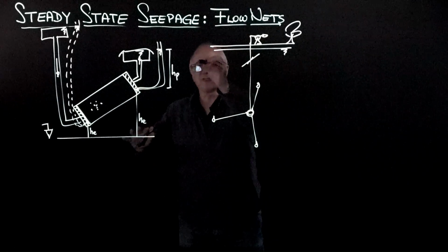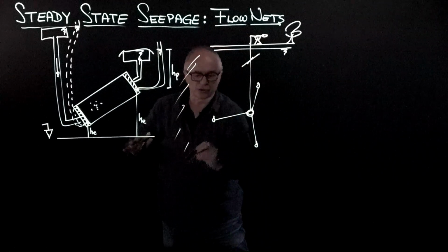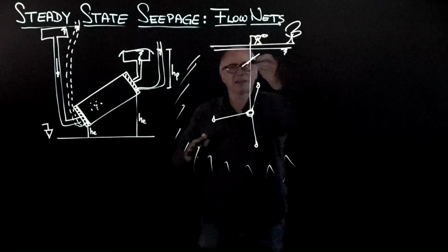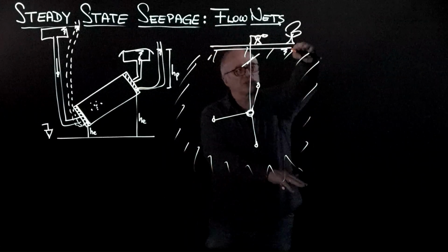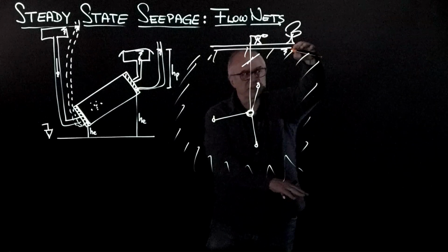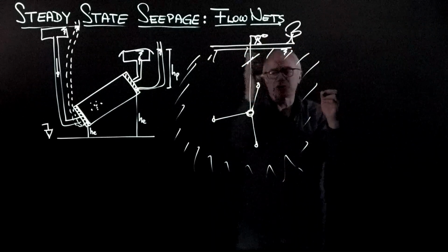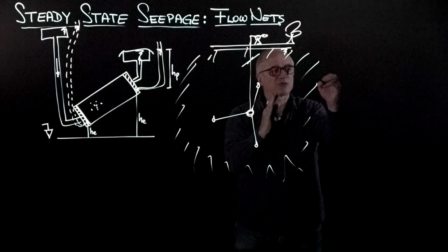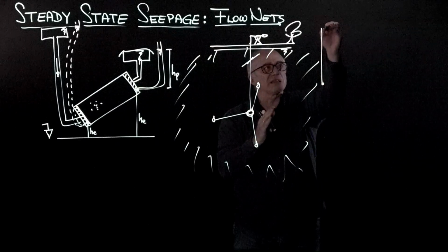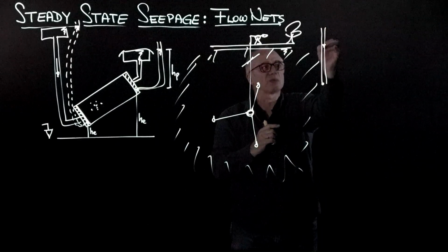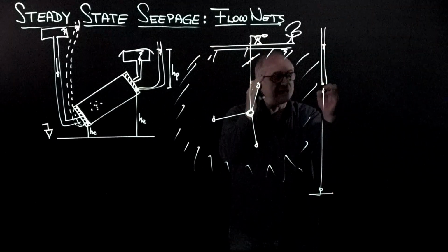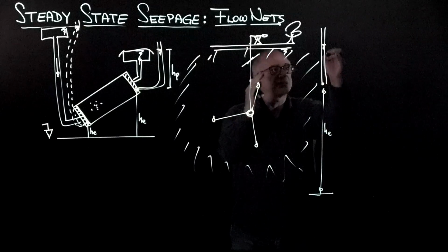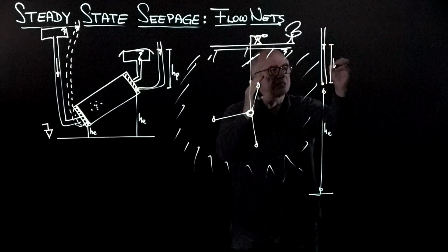So the far field, and it all depends how far you want to put it, the far field here is a far field of constant total head, which is controlled by the water here, because at any point, now forget about pumping, think of a swimming pool. At any point I can place here a piezometer, think how high the water will rise, and from a datum, this is the elevation, H elevation, and this is H piezometric.